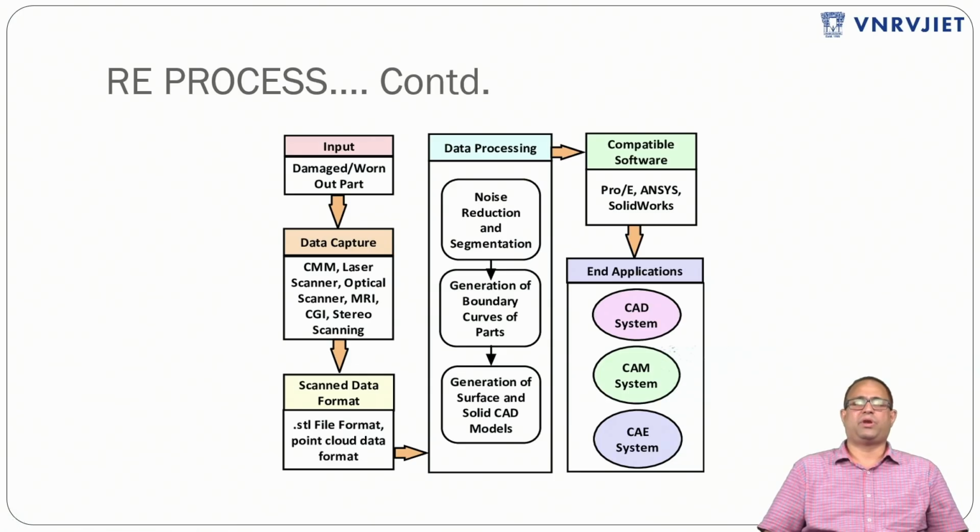So it is completely in mesh format, and then after processing into the mesh format, while doing the scanning, objects other than the scanned part are also going to be captured. All those factors are called noise factors. These noise factors should be completely eliminated, and then we retain whatever part we are supposed to retain. That model can then either be converted into .stl or imported into CAD format to work on the features.